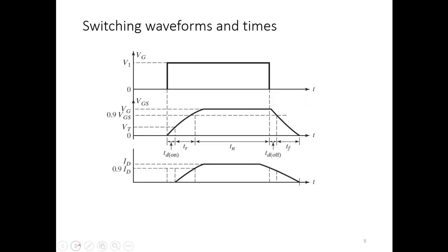Now this is a typical switching characteristic for any power semiconductor device. We mentioned it in chapter 1, as a switch. Here, you apply a gate voltage, virtually like a square wave. Then there is a delay time of the device, there's a rise time, and then the device completely conducts, and there is the fall time, TF, and then the off time.